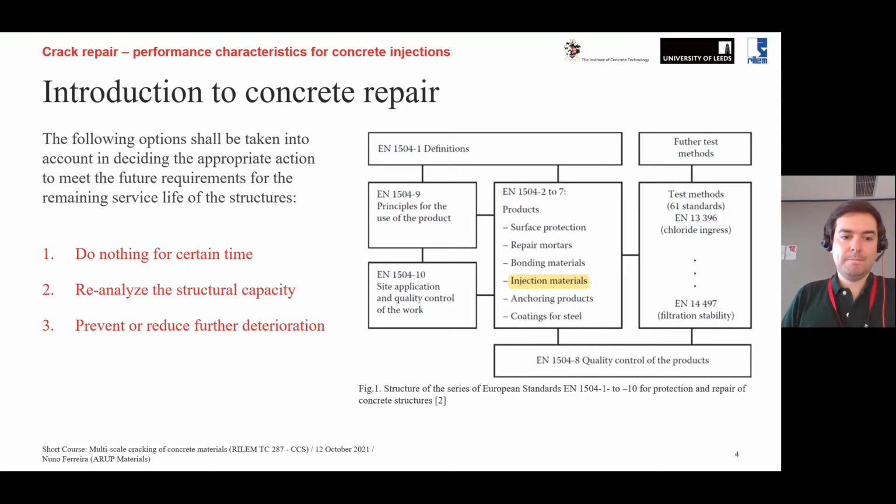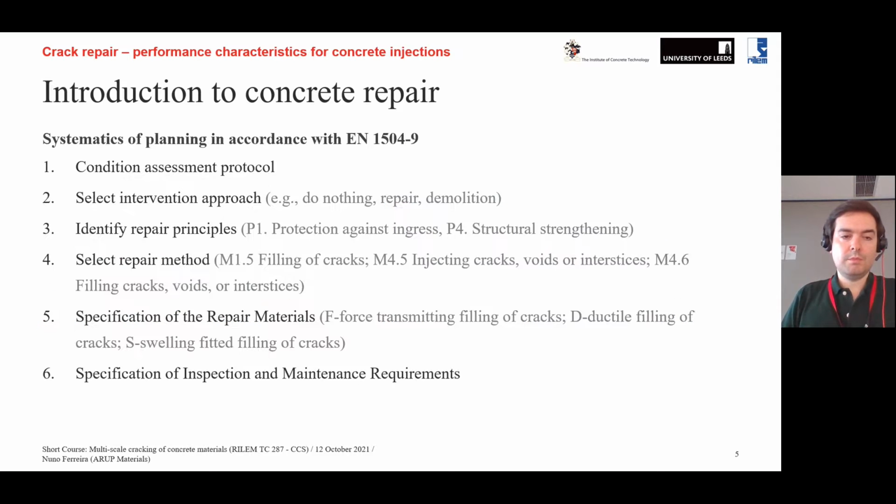Now, if we start with the basics of concrete repair, we can see that there's a little bit of systematics in the approach in accordance with the standard. So first of all, and highly recommended, is to carry on with the condition assessment protocol. And then, going forward, we start to think about the selection of the intervention approach.